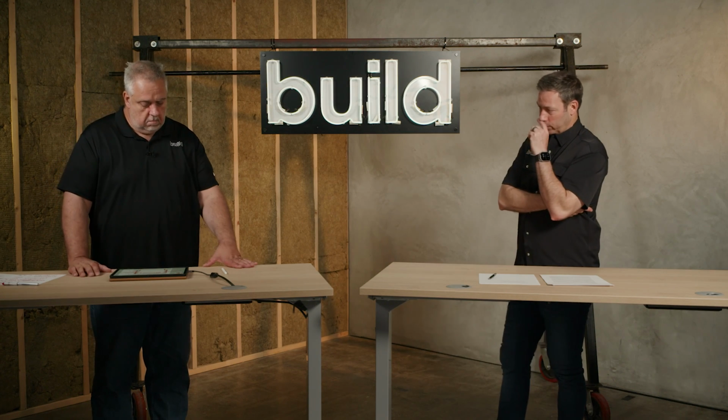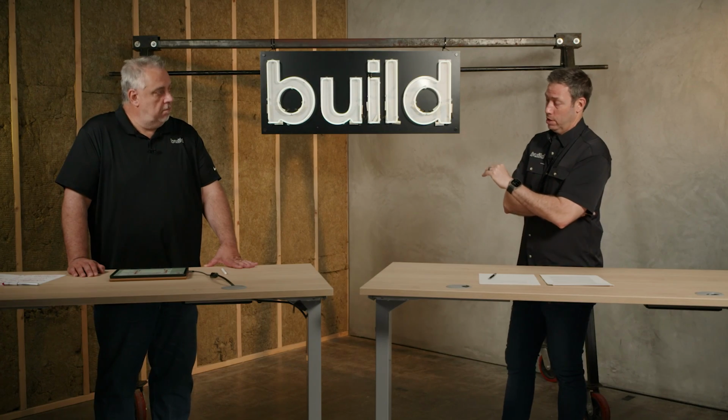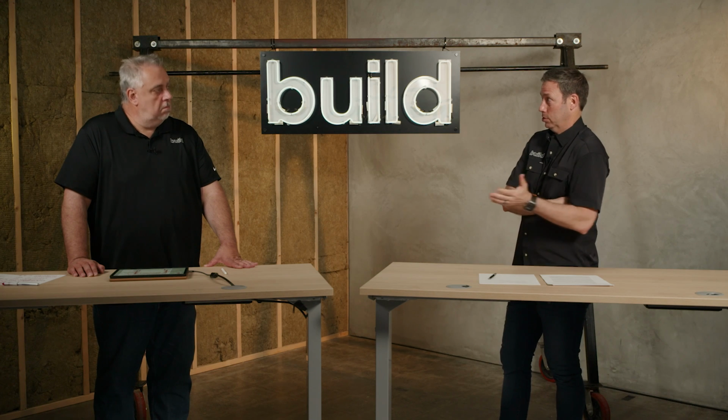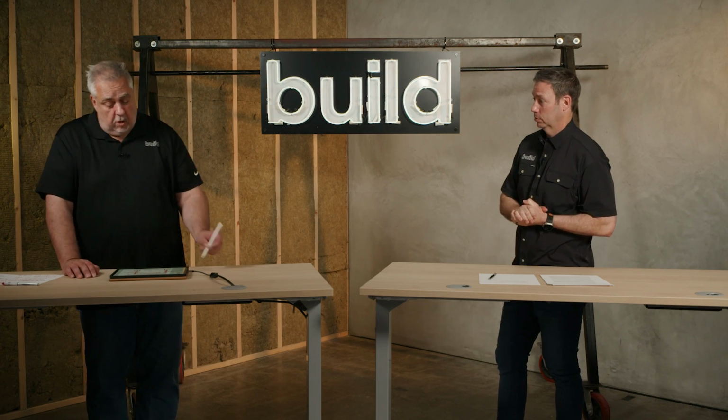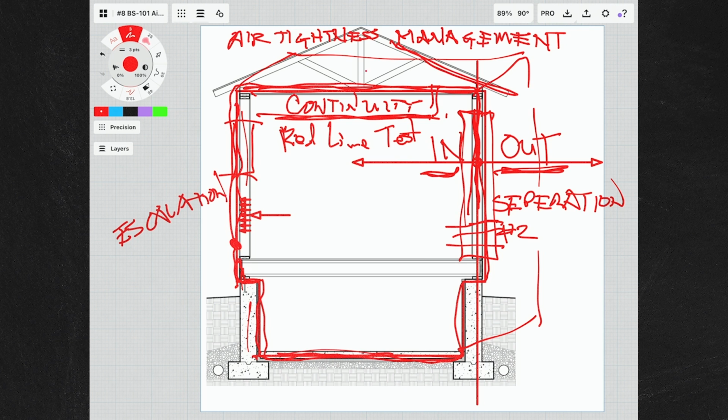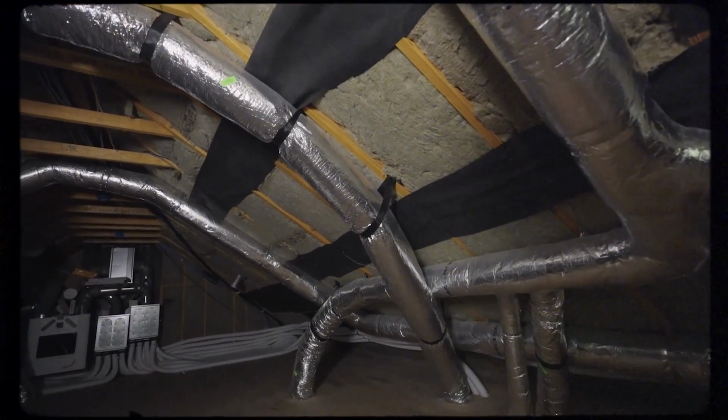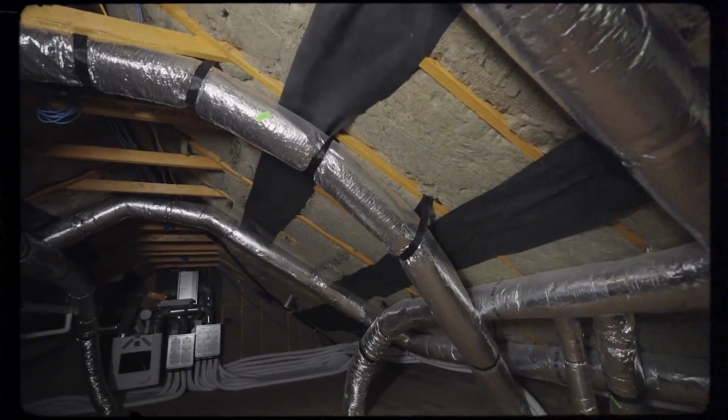And on your drawing set right there, where the top of the second floor or first floor ceiling is the continuity of the air barrier, that means that the attic space above that is outside. Even though you see it as, hey, Steve, isn't the attic inside? Well, it's under the roof. No, it's not. It is outside of my red line, unless I choose to incorporate components of the roof as part of my red line test. Then I could make a conditioned attic. Now, these are the decisions that we make along the design process, right?